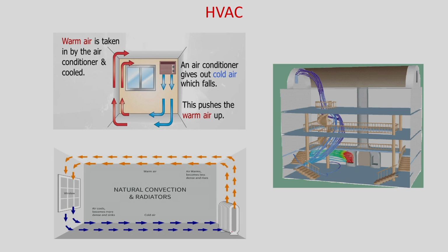Similarly, if you use heater, room heaters or radiator, so here also the fluid which is coming into contact with the radiators, the density will become low and it will go up, and this warm air will flow, and when it will come to some cold place like window, its density will become higher and it will go down, and this way cold air will come. So, there will be a natural convection. In any building, to know how effectively you can cool, you need to have this knowledge of convective heat transfer, so that effectively you can cool the building.